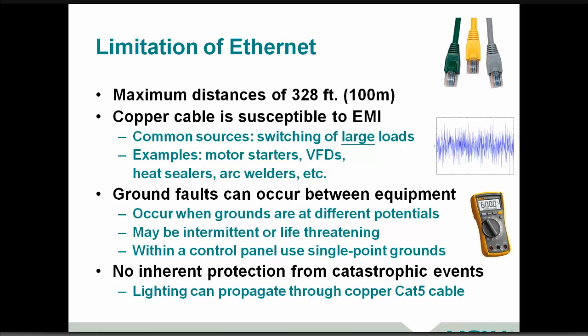Those can always create electromagnetic interference, or EMI, and that can impact what's happening. Fortunately, the design of Ethernet is a really well done design, even dating back to the early implementations for twisted pair cabling, where you have differential signaling that's transformer coupled to basically reduce a lot of that noise on the endpoints, and you can actually sustain a lot and very well.